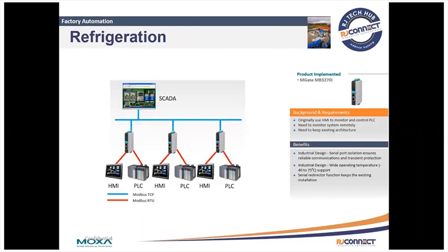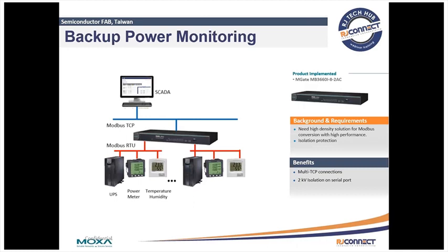A refrigeration application where they had an existing HMI controlling a PLC. They needed the serial redirector function to keep the existing installation working while adding the SCADA system for remote monitoring. Power backup monitoring. The benefits for this customer were multiple TCP connections and also the 2 kilovolt isolation on each serial port.